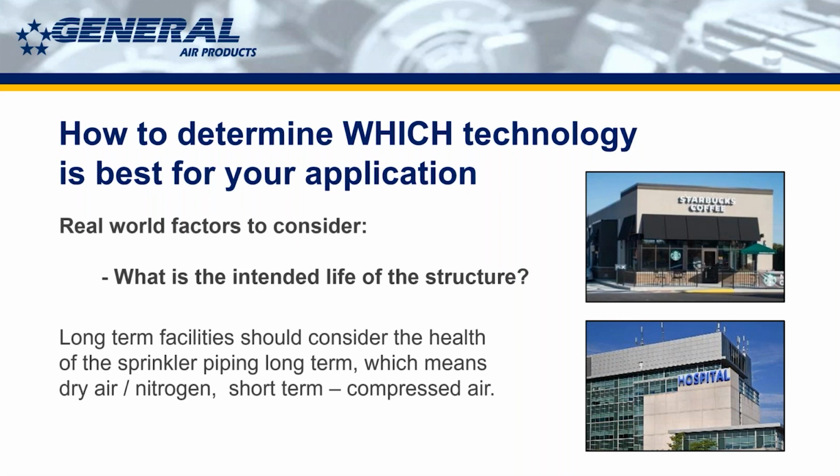That said, a hospital or a university or a museum is going to be that for a long, long time. They're not going to change, so we might as well have a long-term outlook on preserving the pipe, which means nitrogen or a corrosion mitigation solution might be a better choice in those instances. Stadiums are another one I like to bring up, because we always think of them as super long-term, but the average life of a stadium is about 25 to 35 years. So how do we make these things last 25 or 35 years? Because then it's getting knocked down.